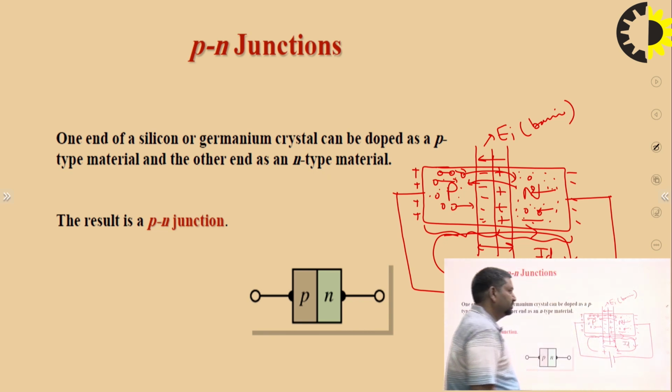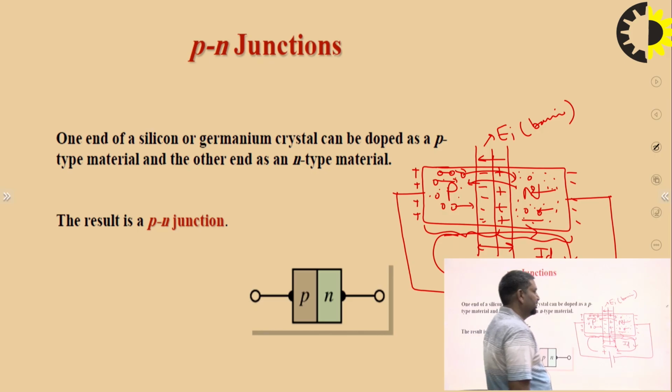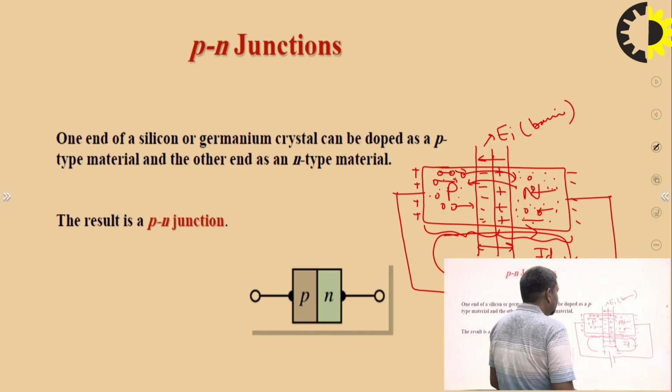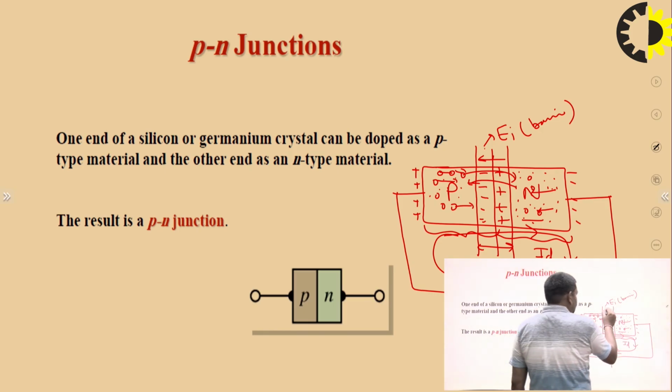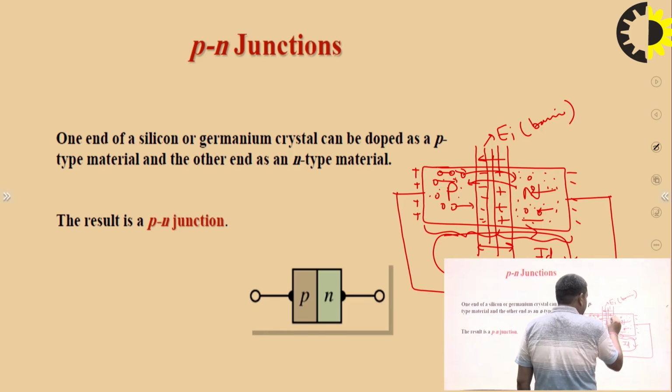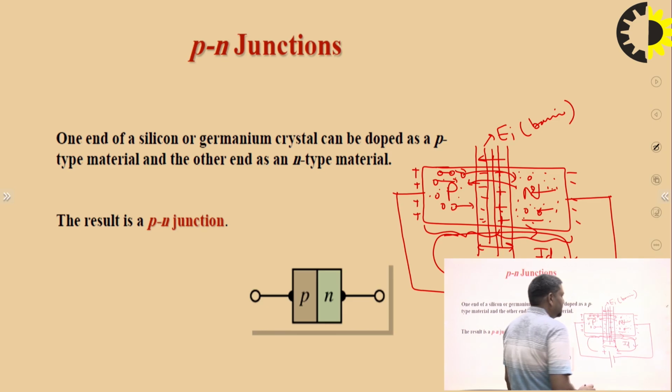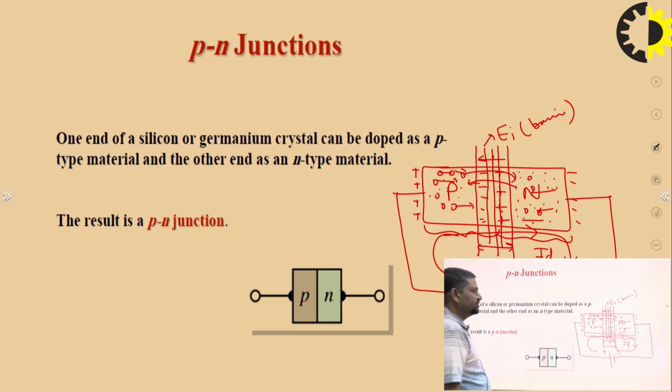This current is called the diode current. In that case, the electrons flow easily from N to P, and the holes flow from P to N. So the depletion width is reduced. In that region, the depletion width is very small, and the diode resistance is also low.